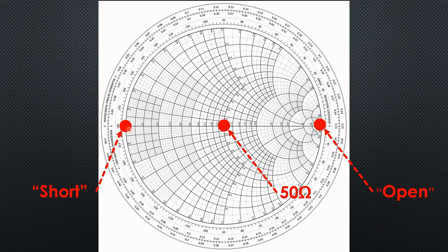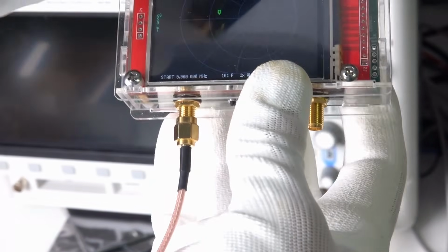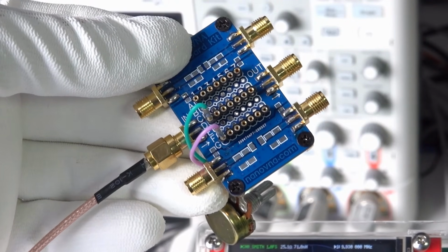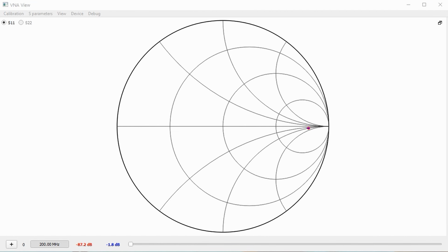I show you that in an example. I have a 500 ohm potentiometer connected to a NanoVNA. You see what happens if I change its resistance from 500 to 0 ohms. The point moves along the center line. Only in the end it turns away from the line. Why? Because the potentiometer also behaves like a coil and therefore has an inductance, which is added to the resistance. I did not know it, but the VNA detected it as a small phase shift between voltage and current, a sign that an inductance is in play.